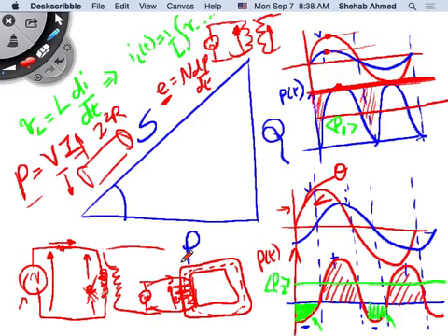So what Lenz's law says is because the input current created flux that moved in the core, the flux responded by creating voltage across each of these turns. And the sum of the voltage across these turns is what creates this back EMF voltage. This back EMF voltage is the reason why the transformer input current is not infinite.